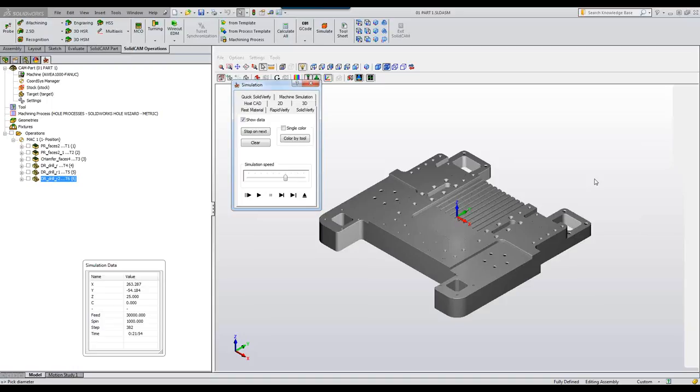In other words, you notice it's a single tool operation, but it drilled on multiple levels in this particular case to multiple depths. If I would have to do this separately, I have to pick out the geometries separately for each one of them, pick my upper level, pick my lower level for each one of those individually, and then do the operation again. Over here you can see as far as the depth, it picks out all of them in one operation.